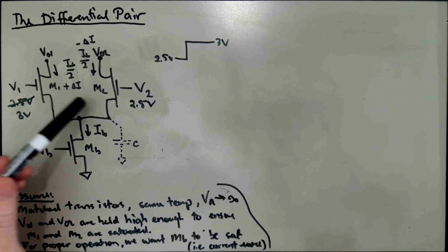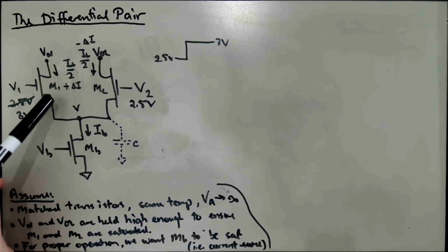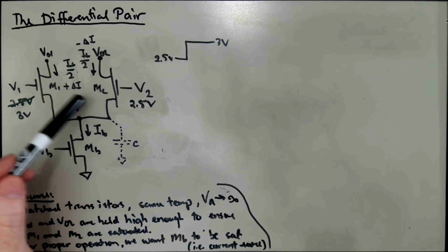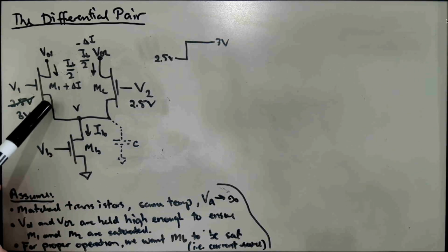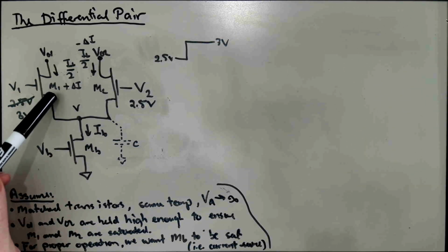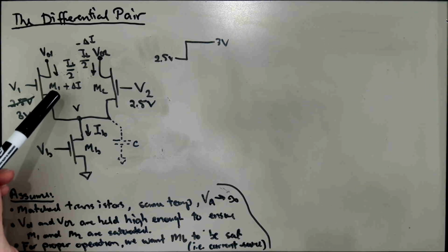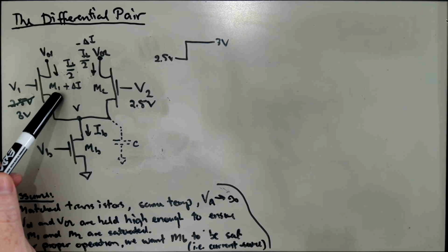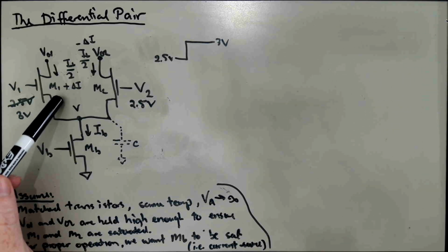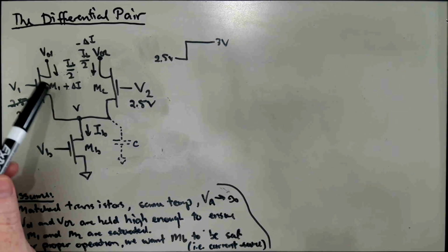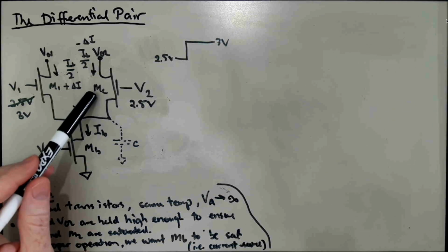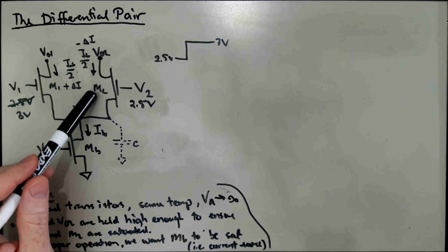And that will turn up the current in both sides here, because we're decreasing the source voltage, and that has the effect of increasing the current in the two transistors here. And that will increase the current here above IB over 2 and increase this above its initial decreased value. But the net result would be that the current here would be less than IB over 2 at the end of the day and more than IB over 2 at the end of the day over here.